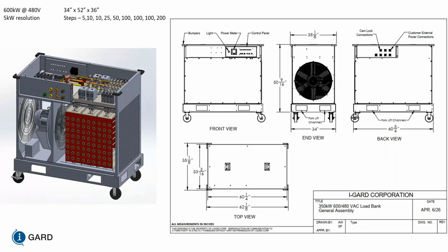For medium voltage, this is a question by Leo: do we have transformer type or direct connected type? I assume this is for medium voltage connections. We've worked with both. You can have a 600 volt load bank connected to a 4160 to 600 volt transformer and test the 4160 volt side.